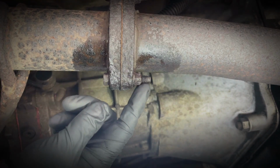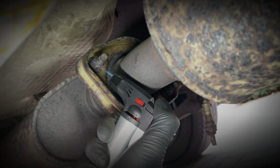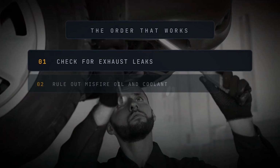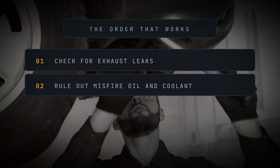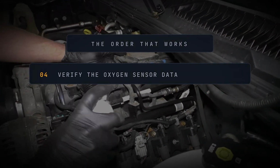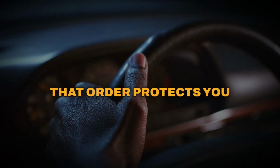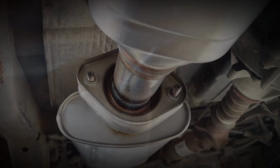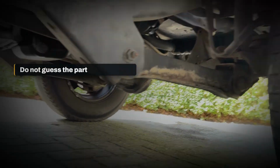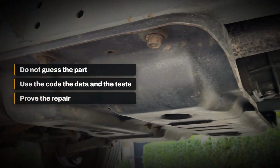P0420 may lead to a catalytic converter replacement, but the code alone does not explain why the monitor failed. Save the evidence. Check for exhaust leaks. Confirm that the engine is not misfiring, burning oil, losing coolant, or operating with a fuel control problem. Verify the oxygen sensor data. Then confirm catalyst performance using the correct procedure. That order protects you from replacing a good component. It also protects a new converter from the problem that damaged the old one. Do not guess which part the car needs. Use the code, the data, and the test results to prove the repair.